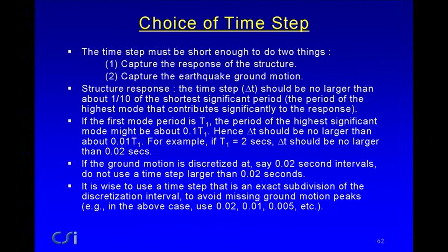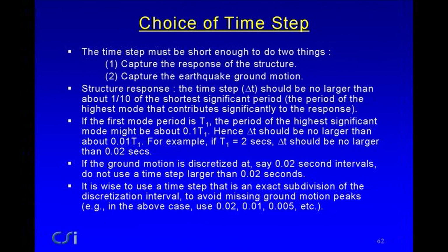Choice of the time step. The time step must be short enough to do two things. It must capture the response of the structure, and it must capture the earthquake ground motion. I'm not going to go into this in detail, but you can take a look at these indications of what you might do to choose the time step. It shouldn't be too long, and if the ground motion is discretized at, say, 0.02 seconds, you shouldn't use longer than that. And if you use shorter than that, you probably should use a whole divisor of 0.02 seconds, because otherwise some strange things can happen.